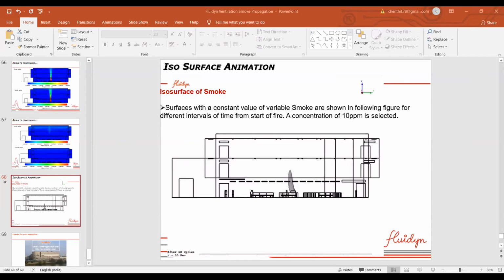Basically, in this method there are built-in 3D domains that we can drag and drop. We have a cuboid domain, and an orbital domain also. Walls we can introduce, openings we can introduce, occupants we can introduce, whatever we want.